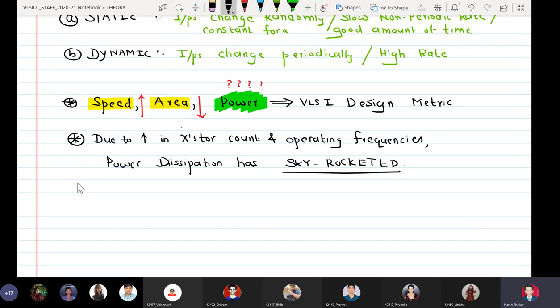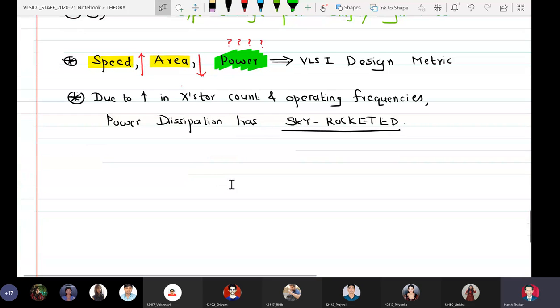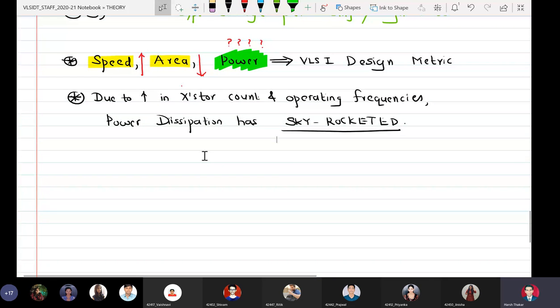That is why we see that even Intel and AMD, when they started competing after 2005, their focus was never the operating frequency in gigahertz or the area, but all of them started working on power optimization. That is why I always mentioned before that all Intel's architectures after Haswell, and the lake architectures like Rocket Lake, Ice Lake, Tiger Lake, Coffee Lake, are all aimed at reducing the dynamic power dissipation of chip.